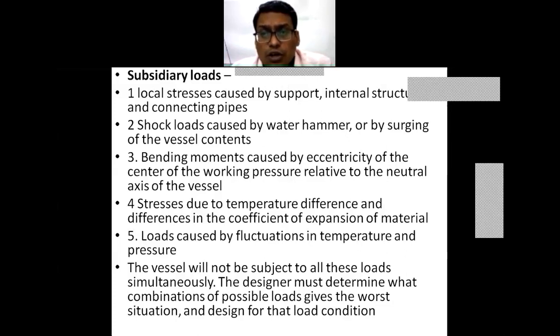Then shock loads caused by water hammering, steam hammering, or by surging of the vessel content. Suddenly the vessel contents increase because of certain failure of the equipment or failure of the control valve. Then the bending moment caused by the eccentricity of the center of working pressure relative to the neutral axis of the vessel. The different attachments are there. If all the attachments are on one side,